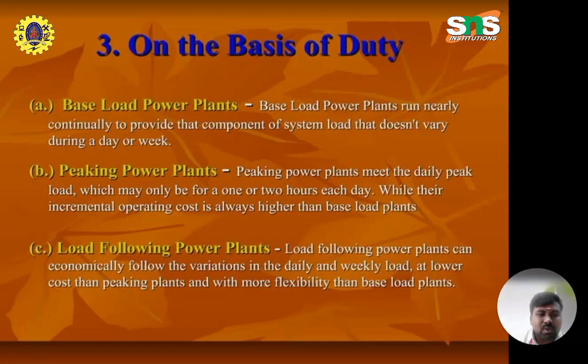The third one is the load following power plant. The load following power plant can economically follow the variations in the daily and weekly load at lower cost than the peaking power plant and with more flexibility than the base load power plant.